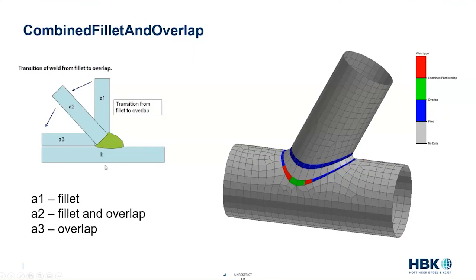It then uses that information along with the weld elements to identify all the parent metal elements that are touching the weld toe or weld root and classify them. The blue here being fillet welds, where they're primarily perpendicular to one another. The green being overlap, where they're almost parallel. And then you'll see that the red sections in here are in that transition region where they weren't exactly overlap or fillet, so we're doing both calculations. But we automatically find the proper locations to do these calculations on.